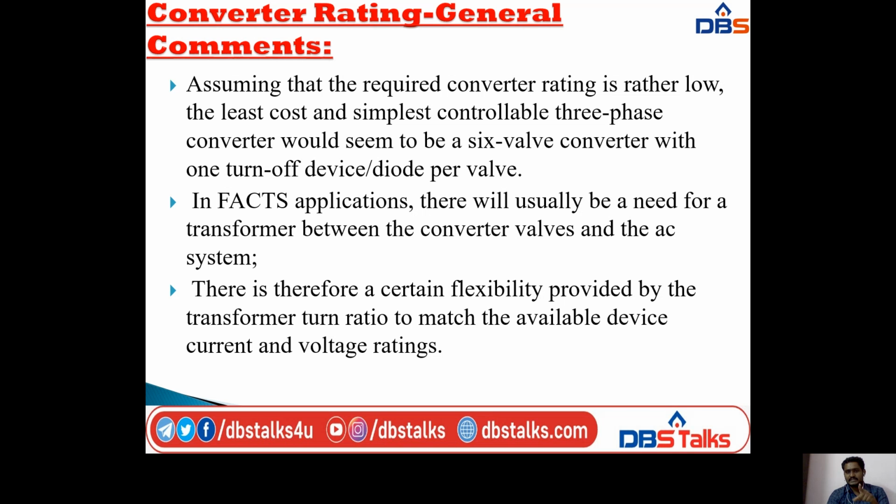The least cost and simplest controllable three-phase converter would seem to be a six-valve converter with one turn-off device or diode per valve.